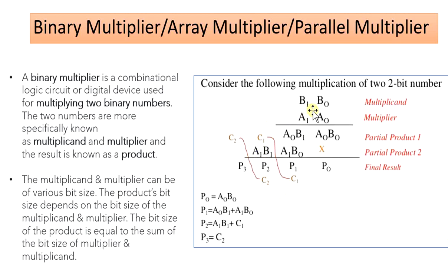So if you had to multiply, say, 3-bit numbers, then you would have obtained a few more terms wherein each partial product would be one left shift relative to the previous one. So in general, I can say that multiplication uses n shifts and adds to multiply n-bit binary numbers.